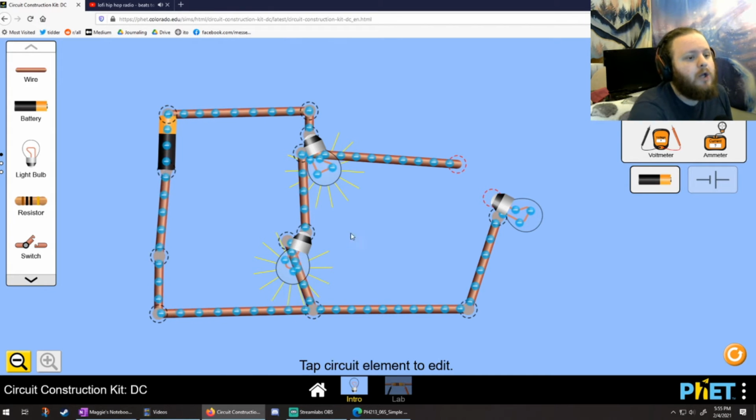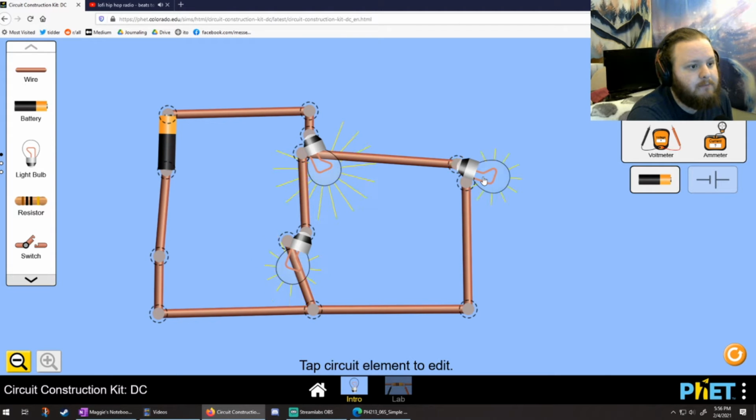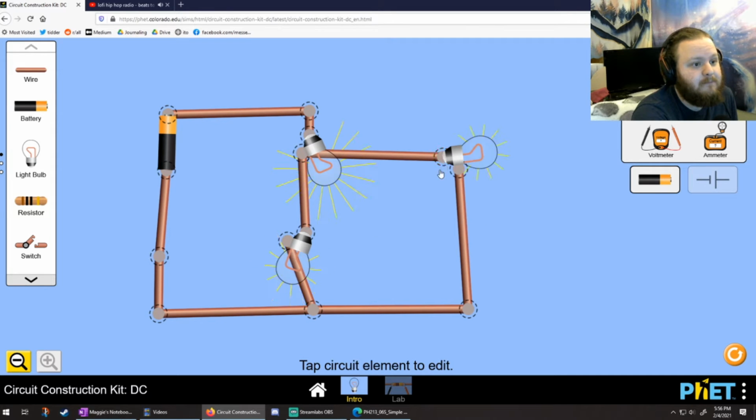That's kind of cool. So now my prediction was, if I click this together and I attach the second piece, what I'm going to see, actually, I don't want current. Go away. What I predicted I would see is that A is going to get brighter and B is going to get dimmer, but B and C need to be the same brightness. I did a thing. That's exactly what happened. If I disconnect this one more time, my prediction was that bulb A will get brighter, bulb B will get dimmer, and B and C will be just as bright. Voila. And that has to be true.